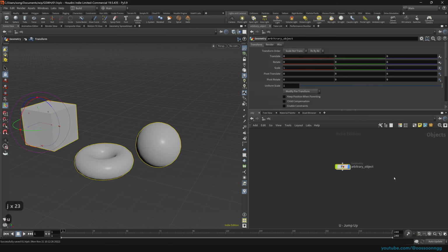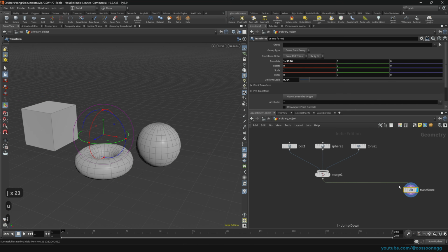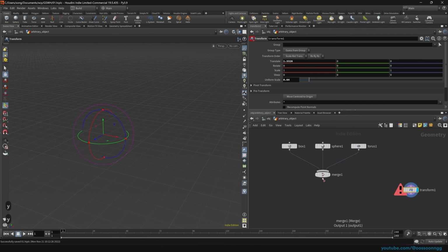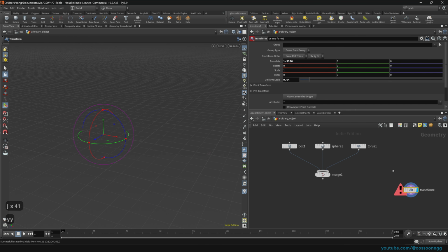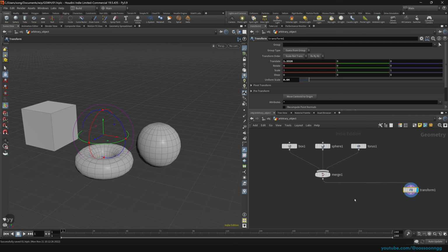However, I find this a little bit not as great as holding down the Y key, because Houdini is smart enough that it actually connects, as you can see, really far away. However, the join key doesn't do that. You have to be a little bit more precise. So the Y key is a scissor that can destroy a nodal connection, and left mouse button drag brings it back.